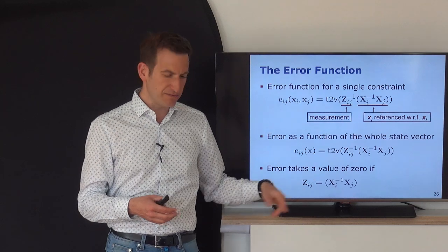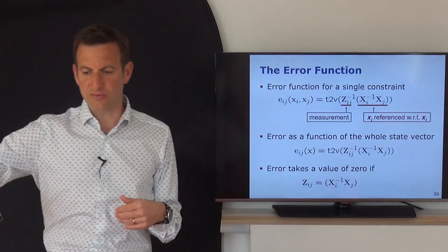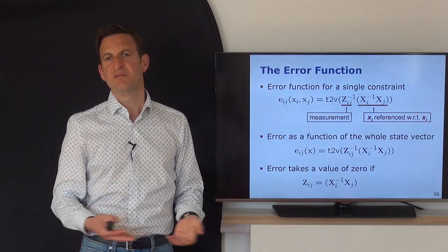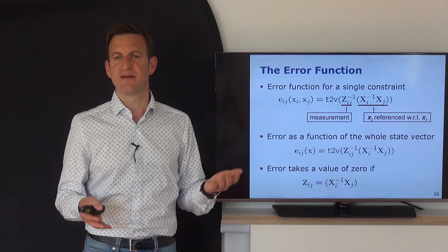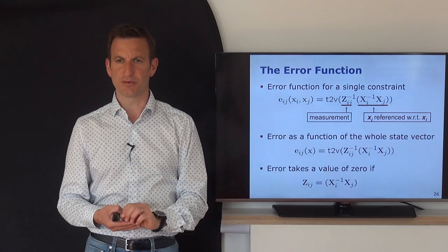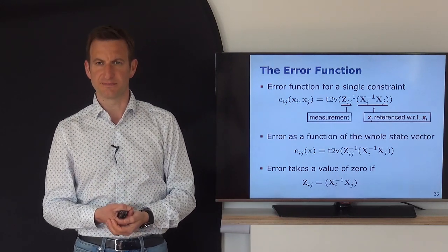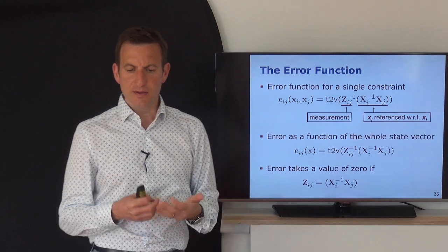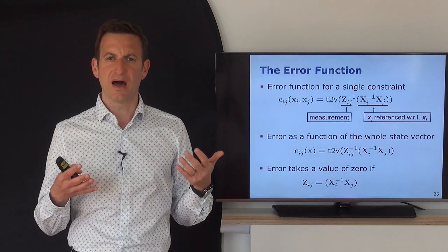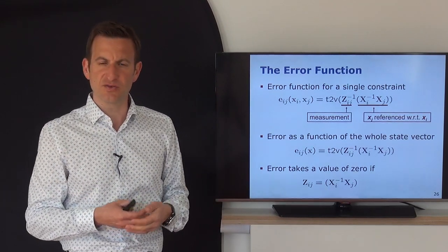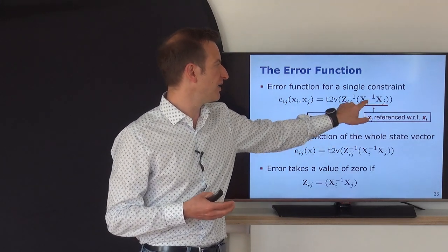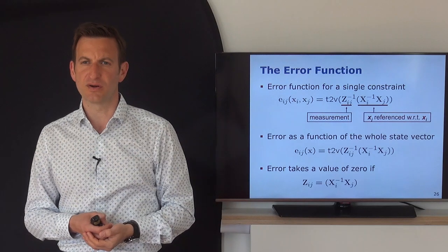So that means if the transformation through the graph and backwards through the inverse of the observation gives me the identity matrix, there's no transformation mismatch. The identity matrix would then be mapped through this function to 0, 0, 0, so a zero error vector. Okay? So the only thing we need to specify is how we get z, and that is a result of the ICP algorithm, just put into a homogeneous vector, and these are just the poses in my pose graph expressed in homogeneous coordinates.